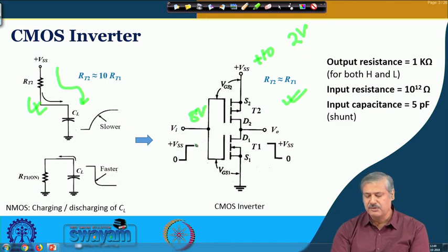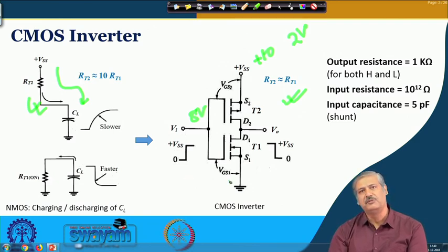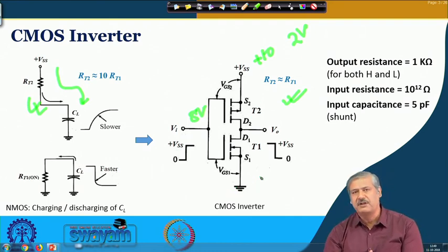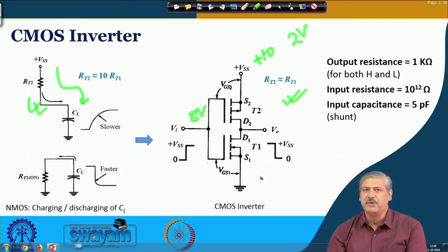And the other case, when it is 10 volt, right, so this is 10 volt, this is 10 volt, so it is not sufficiently negative, this particular junction, right. So, no P channel is formed, but this particular input is sufficiently positive above the threshold voltage, so the N channel will be on. So, at any given point of time, you have either the PMOS or the NMOS on, okay, and only during transition or the switching, both of them can become on.